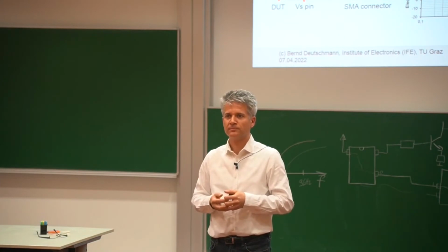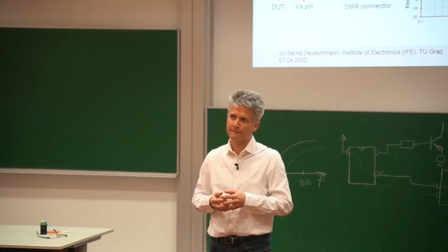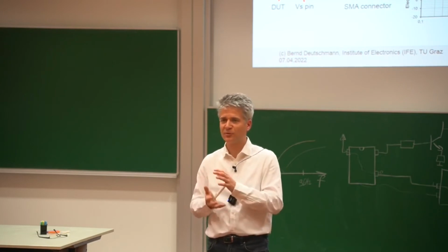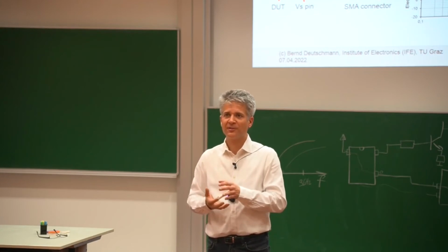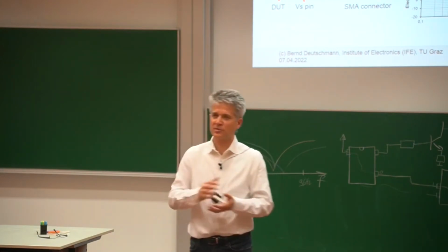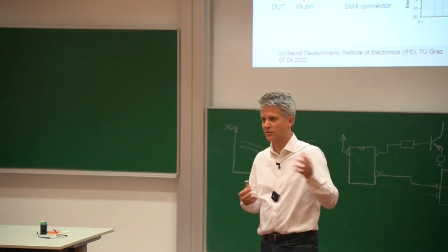I think it's better to produce than a P-channel, so it's a smaller die size for the same ISO. Mm-hmm. Yeah. Faster, smaller, better. It has something to do with the mobility of the charges. So in the N-channel transistor, it's the mobility of the electrons, and the P-channel transistor is mainly the mobility of the holes, or the defect electrons.